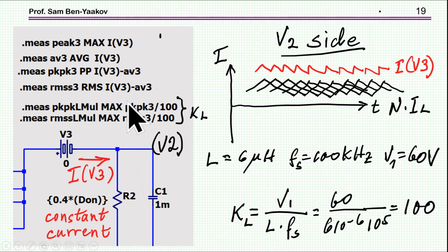Now we go to the LTspice way of getting the information. There is this directive of measure, okay, which is associated with the step function. I am defining parameters that I'm extracting. This is the syntax of LTspice. This is an operator: find the maximum of I(V3).